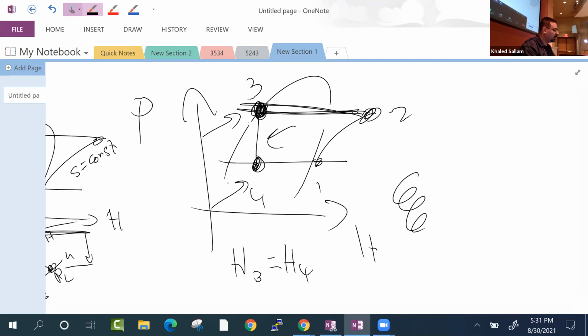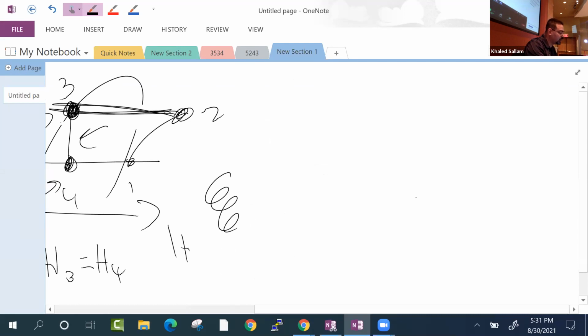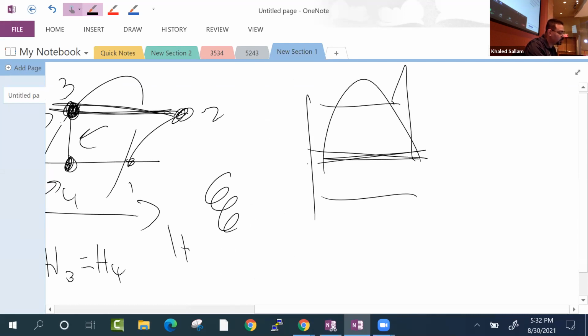I mean, remember in the Rankine cycle, and we said in the project, how you have to do what? You have to set yourself a limit: I cannot get any wetter than this. There is an X here. When I'm coming down in my turbine, I want this turbine to live. Therefore, I'm going to limit myself to X, I don't know, 0.8, 0.9. You guys will figure it out. But we said, you cannot go there. So now how are you telling me to come from here and expand in a turbine? That will be the end of that turbine, right?